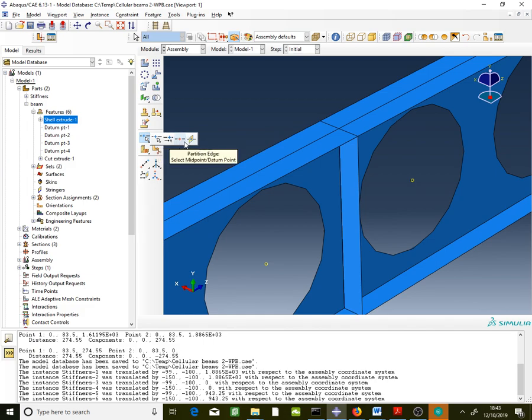So what I can do, before we carry on, is press X. I will place a datum point. So for a datum point, if you click here and you keep pressing, choose the one which says offset from the point, and you take the offset from here, and it's in Z direction, -20, and you hit enter.